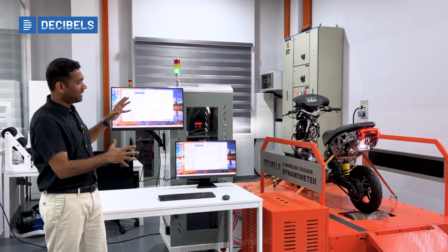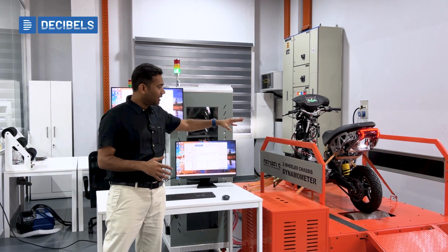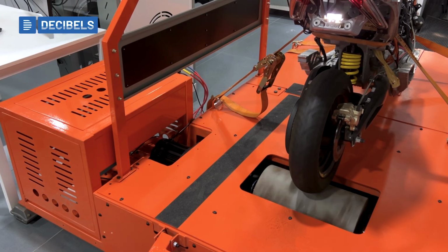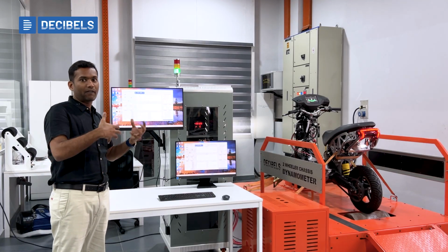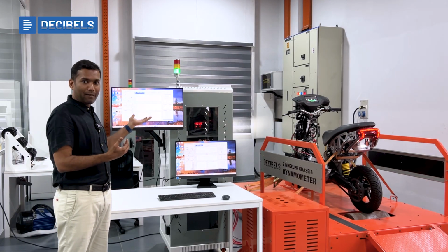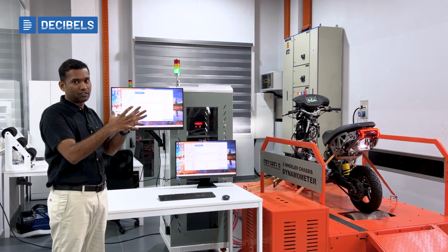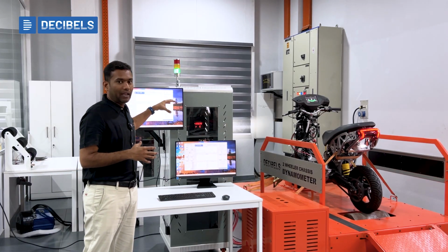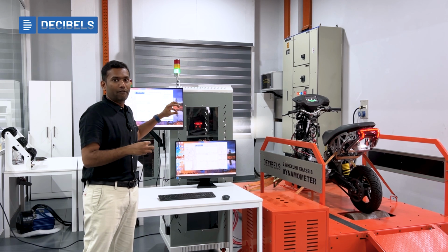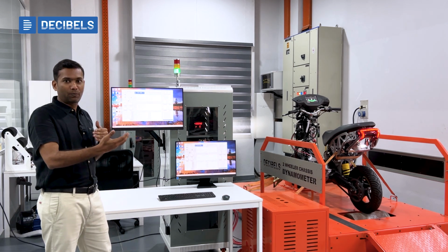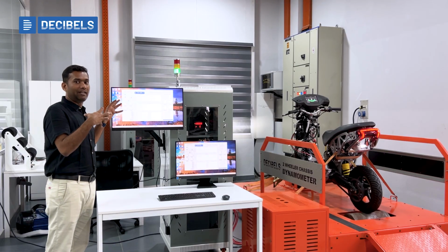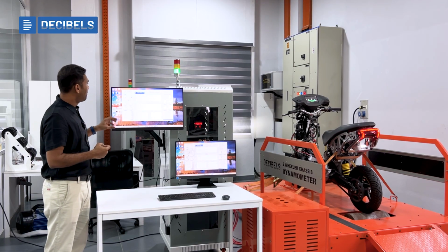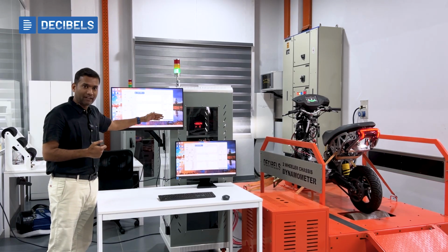What we see here as a test setup consists of the mechanical infrastructure where we can load the vehicle, and also a roller and a 4-quadrant load that is sitting in the bottom. And then this rack consists of all the power control modules and also the power supply modules, and then our safety and interlocking mechanisms, and then our indigenously developed hardware and software for the computational activities of the open loop or closed loop controls. Here with this GUI, you're able to completely take care of the test environment where we can conduct different varieties of test cases.